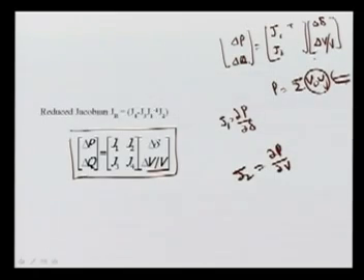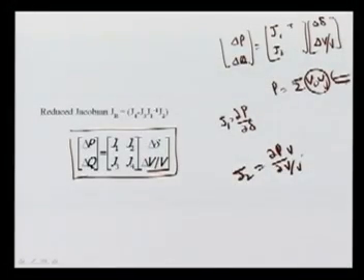As you know, the Newton-Raphson load flow method basically provides quadratic convergence. So we multiply here with V and here we go for V. What has happened? This multiplication gives a complete quadratic and then we get faster convergence. So this is your Jacobian. If we are not changing the real power injection, then delta P will be 0, and we want to see the relation between the change in reactive power and the change in voltage.